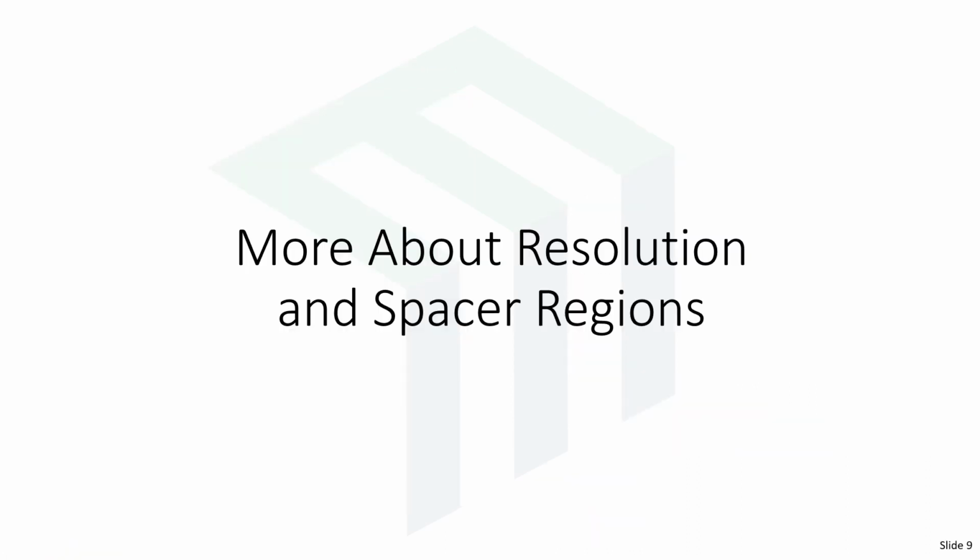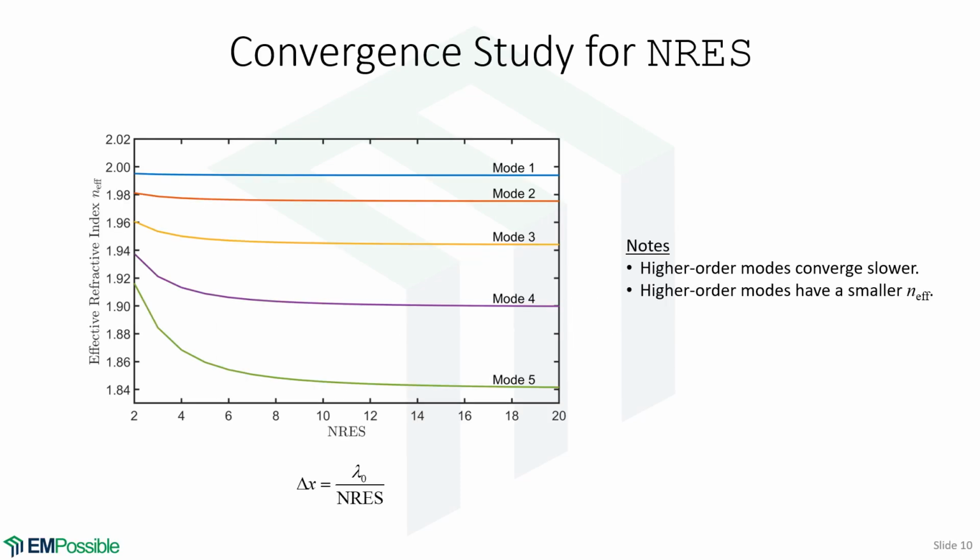More about resolution and spacer regions. So in the beginning, I like to always create a very low NRES, so all my matrices and arrays are very small, everything runs quick, and I wait until it runs without error and I think everything's correct. At that point, before I conclude anything about my answer, I'll always perform a convergence study.